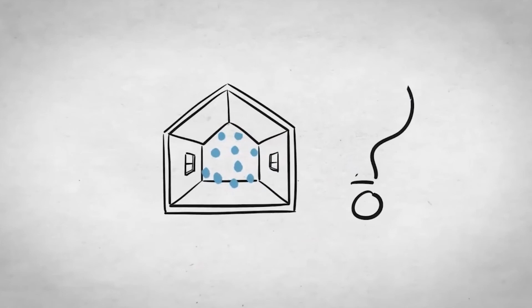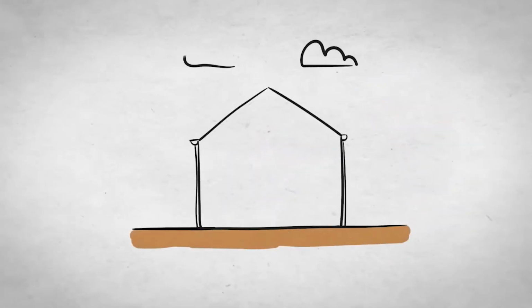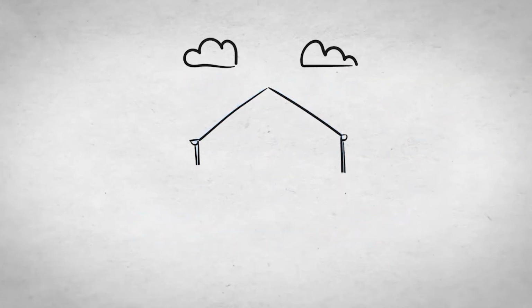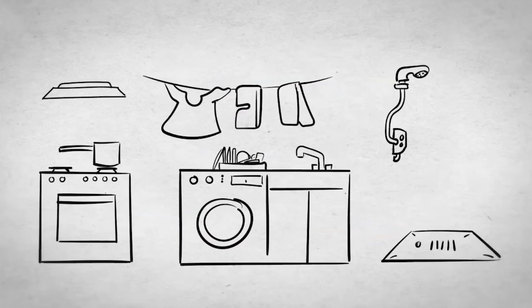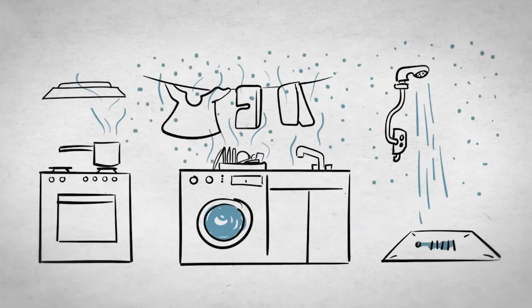Where does the moisture in your house come from? Outside of the home, the most obvious answer is rain. Good construction is vital to avoid water entering a building from the roof, walls and windows, along with suitable ground drainage in the case of flooding. Inside, we have our direct uses of water in our daily lives, washing and drying clothes, cooking and bathing. All these produce visible liquid water and large amounts of not so visible water vapour.